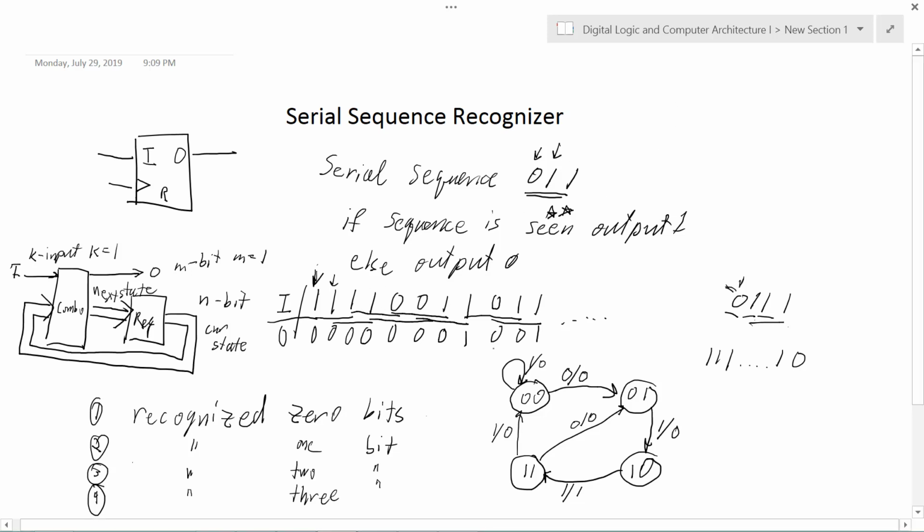So let's take stock of where we are. On state 0, we have an input 1 edge and an input 0 edge. With an input I, 1 bit, that means we need only 2 edges, so we are done with state 0. State 3, we have an output 1 edge and an output 0 edge. Covers all the edges coming out from 3.